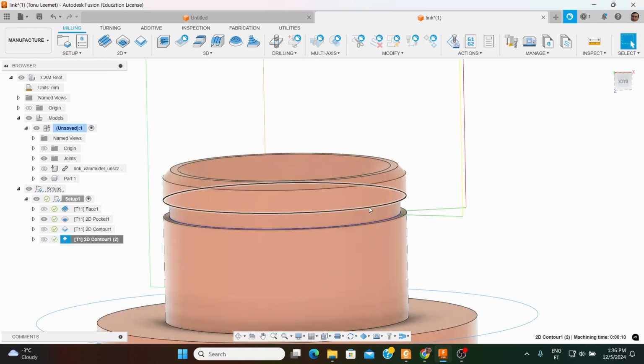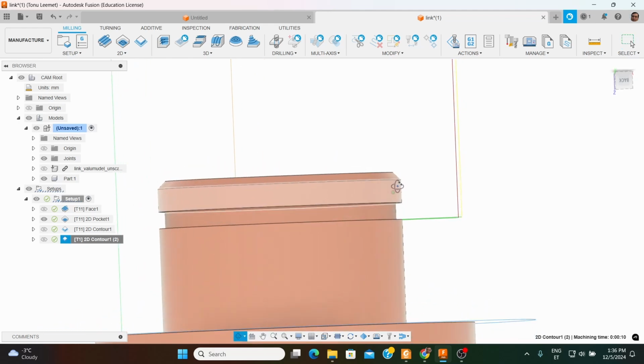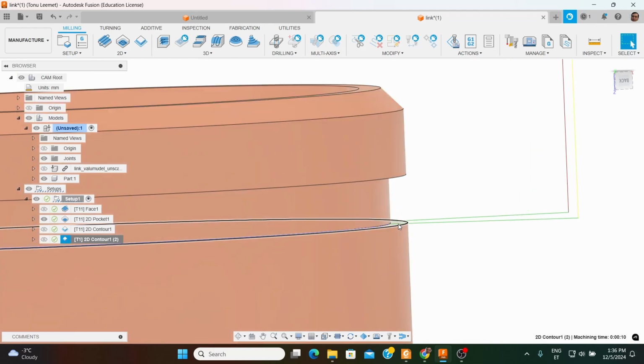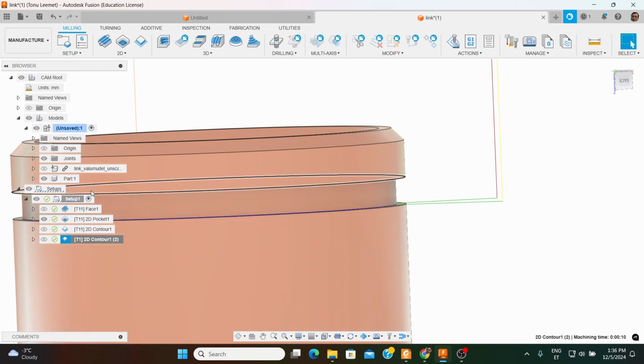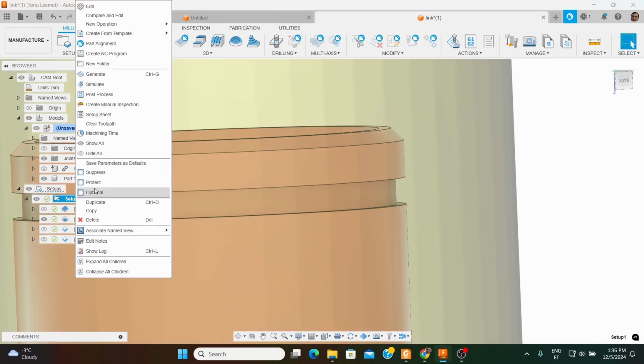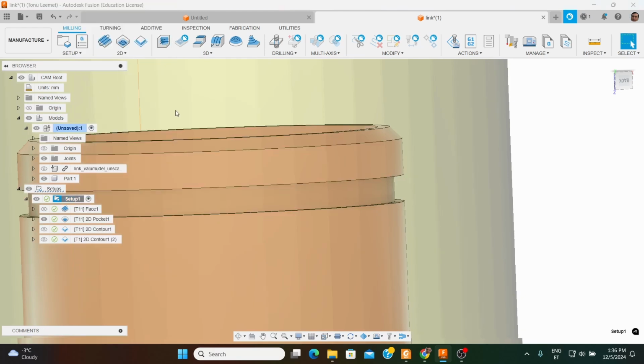You see we have a toolpath, but it is actually not correct, because we must consider that we had a tool that is 1 millimeter, but this particular groove width was 1.1 millimeter. So in reality, it shouldn't machine it in the correct way. Let's double check it with the simulation.